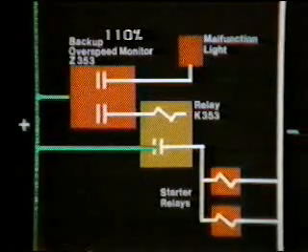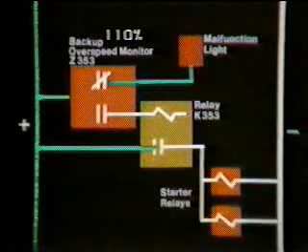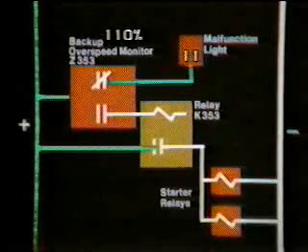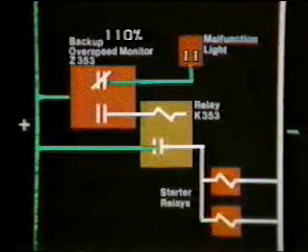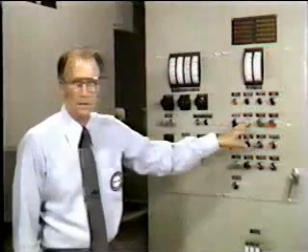The new circuits created by K353 will cause the start-run relays to drop out and malfunction light number 11 to illuminate. Remember, the engine cannot be restarted until you push the reset button, if it has shut down on an overspeed malfunction. The package is protected from explosive gases and fire by 2 other monitors.